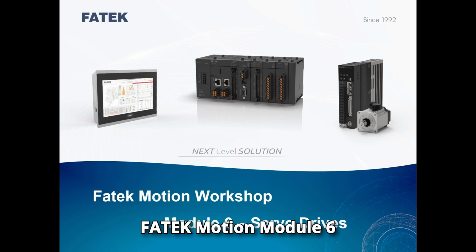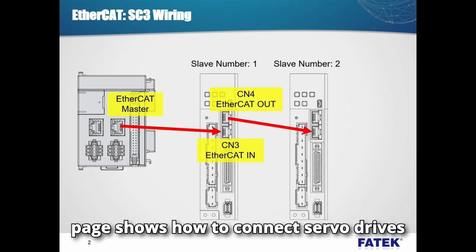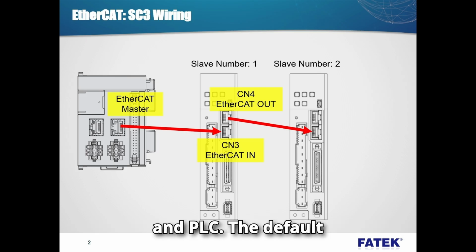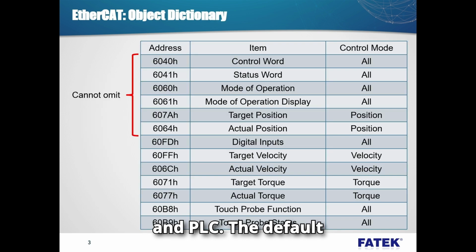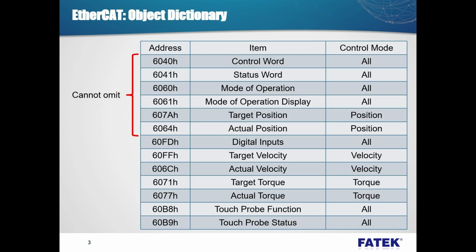FATEC Motion Module 6, Servo Drives. EtherCAT, SC3 Wiring and Object Dictionary. This page shows how to connect servo drives and PLC. The default object dictionary item list is in this page.